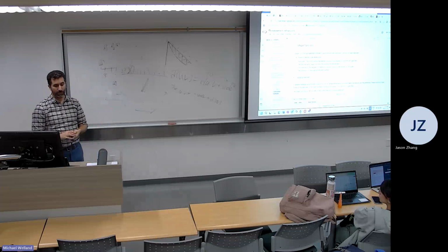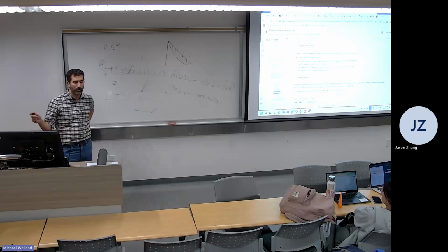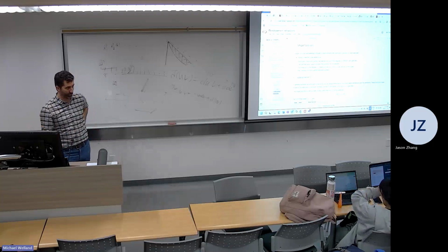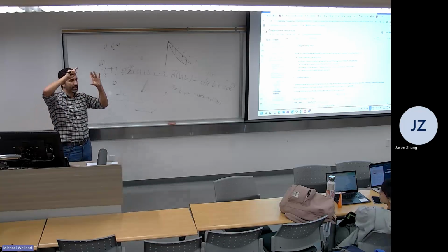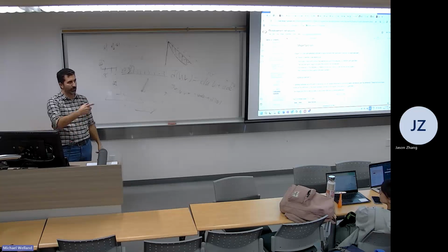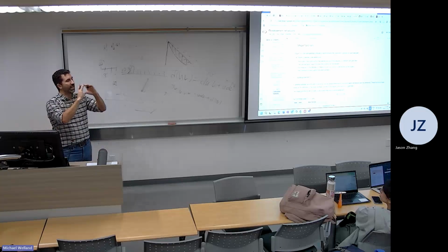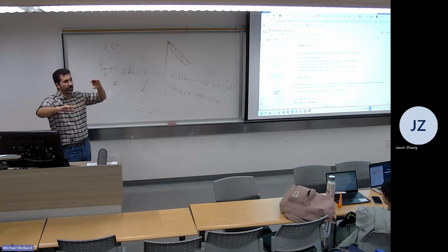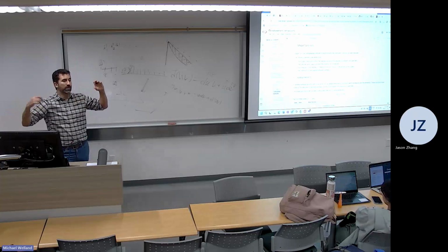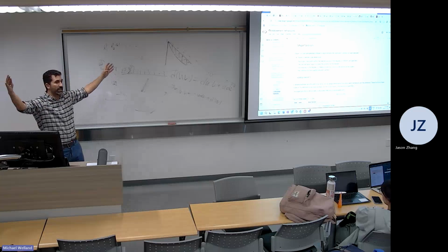Finally, we come down to the shape functions. Shape functions are designed to approximate the unknown function on each element. Typically, what that means is that whatever degrees of freedom are on that element, I'll have to go into more of this on Wednesday because we don't have so much time, that shape function is 0 on all of your other elements. And this is where the sparsity comes in, because your shape functions are technically defined over the entire domain.